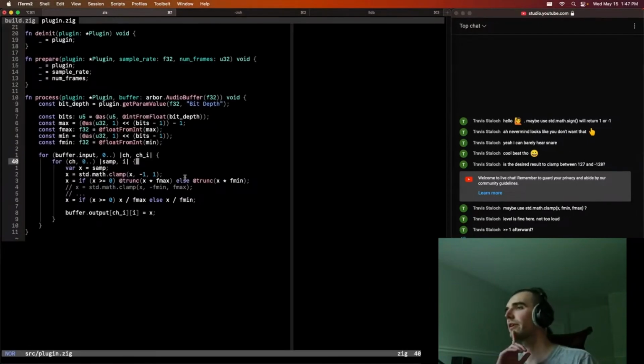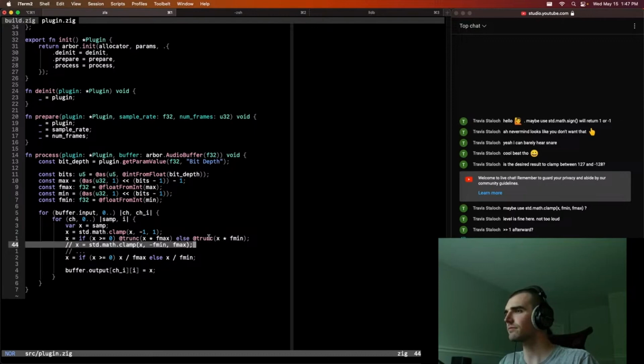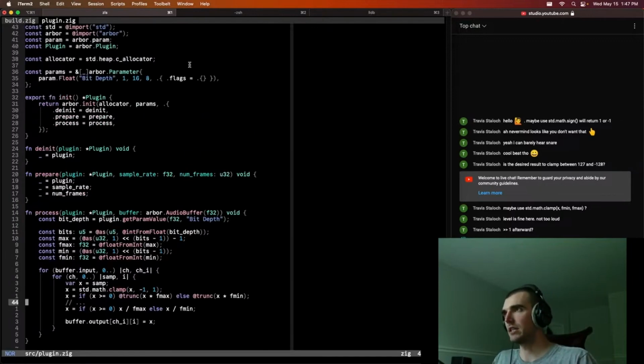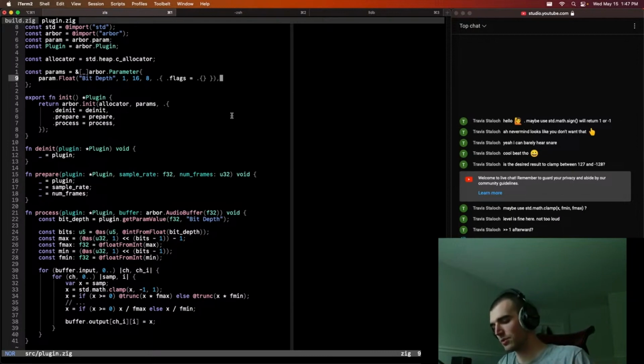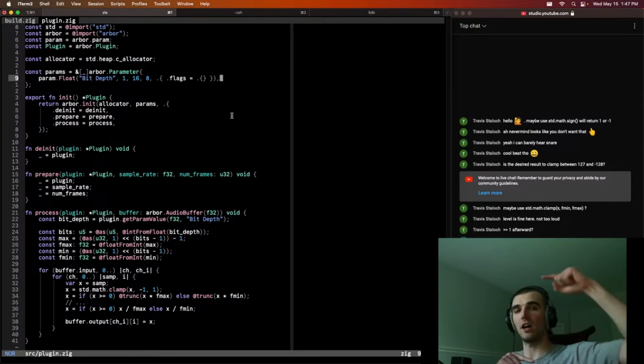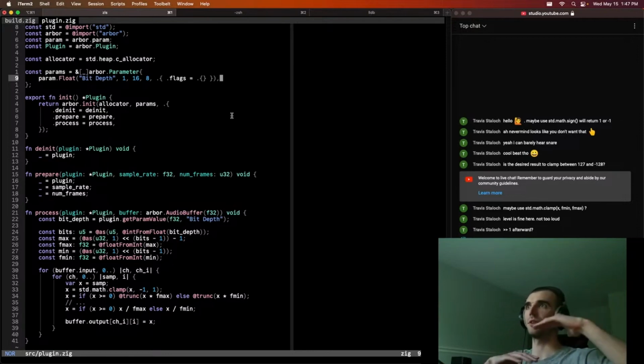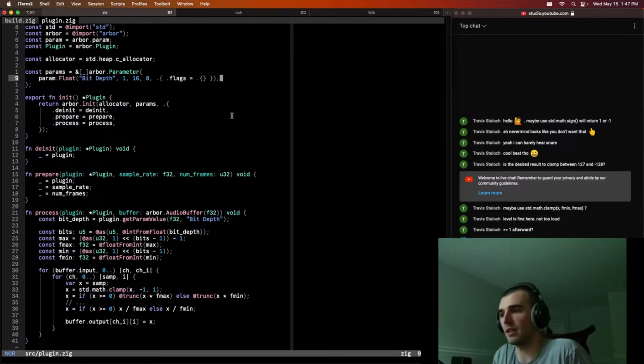And what I want to do now is introduce another parameter, which will effectively be like a gain control, but we'll call it noise floor. What it's going to do is turn down the volume of our signal coming in and then turn it back up after the bit crushing, so that it effectively underfeeds the bit crushing process, so we can actually raise the noise floor.